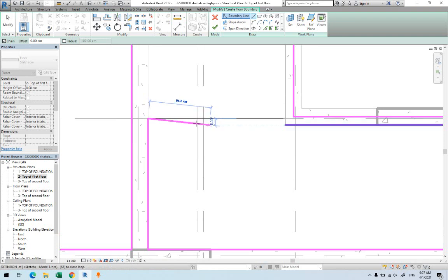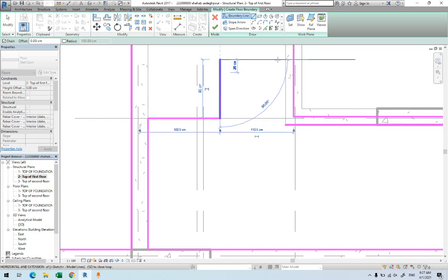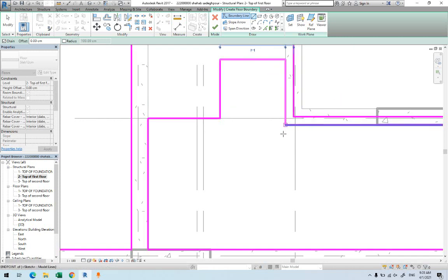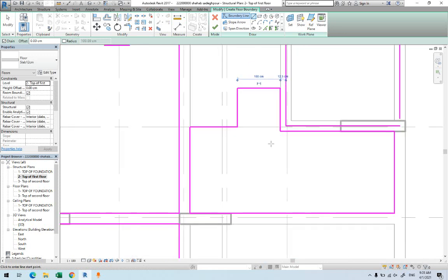Now, if you want to go with the distance, look, so far I'm just clicking on the corners. It's very easy to draw with the distance. You just simply make it horizontal. Let's say the dimension will be 110. You'll just type 110 since it's centimeter. It will draw it like this for you. Let's say I'll go up. Say we have it here 90 centimeter. Goes like this, and when it reaches an intersection, it will give you points. Now when you come back to the first point, automatically the drawing will be inactivated.